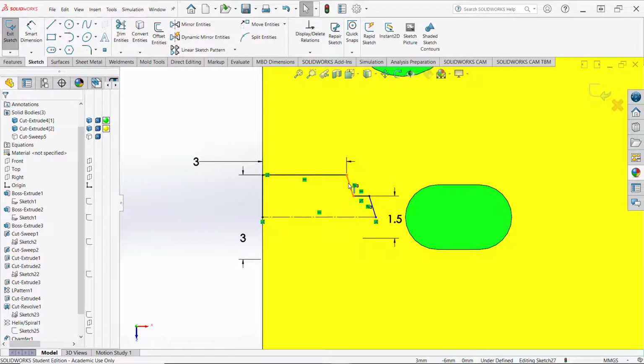And now on these angles, a standard drill point is 118 degrees, or 59 degrees halfway. So on the original file, the angles were at what I would term strange sizes.